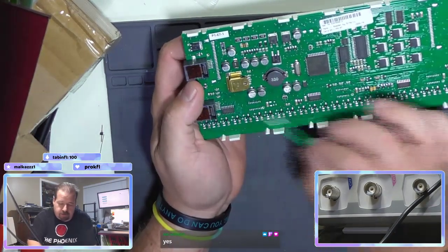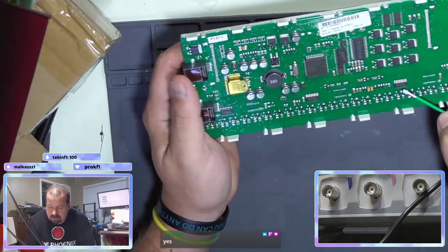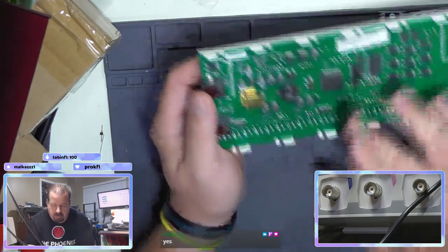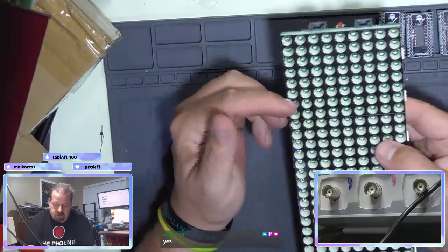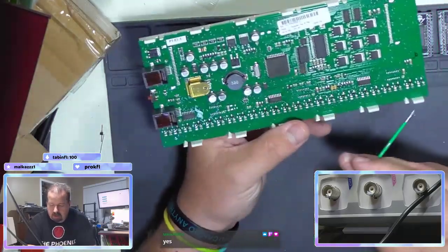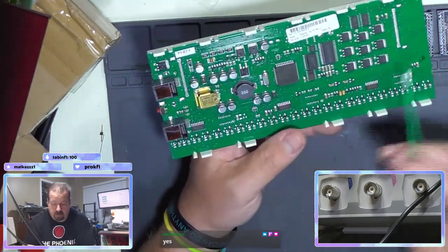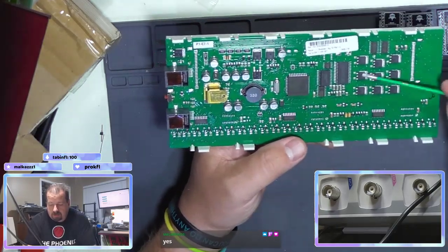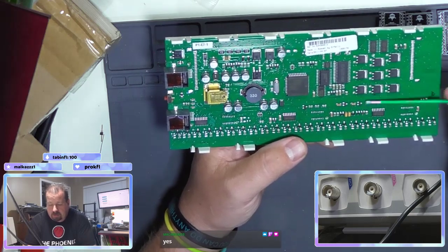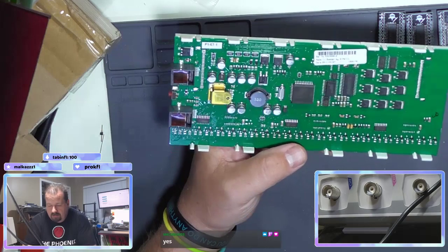These column drivers are driven by three 4094 8-bit serial chips. The display does support two colors, but there's only one set of colors. The second color transistors aren't loaded. The second 4094 drivers aren't loaded. Each row is driven by one of these transistors. These look to be driven by, again, 4094s.